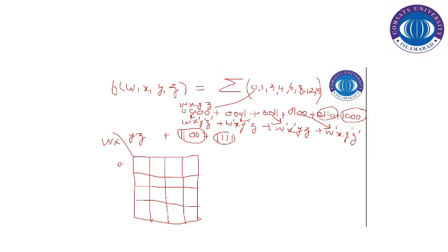So that is 00, this is 01, this is 11, and this is 10. Similarly for the columns as well, this is 00, this is 01, this is 11, and this is 10. And we have to place those minterms in the map. For example, minterm number 0 is 1, minterm number 1 is 1, minterm number 3 is 1,